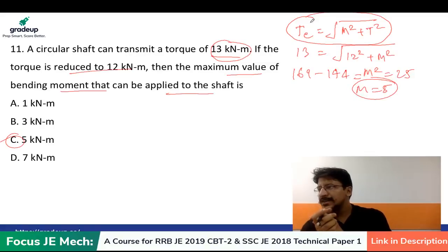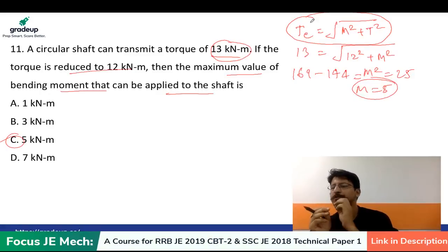See, shear stress is maximum and normal stress is 0. There is no such plane which exists. There are 3 planes which exist. One is your principal planes, on which the shear stresses are 0. Normal stresses are either minimum or maximum, and the shear stress is 0. Then there is the second plane, that is your plane of maximum shear stress.